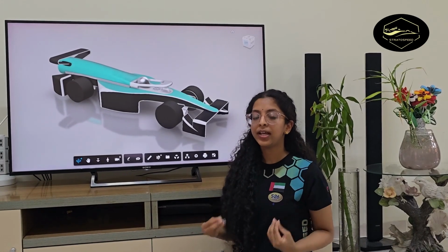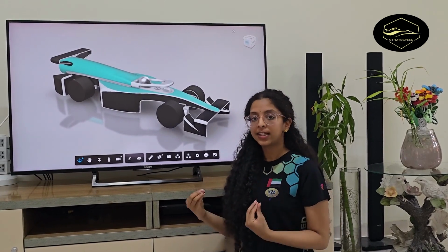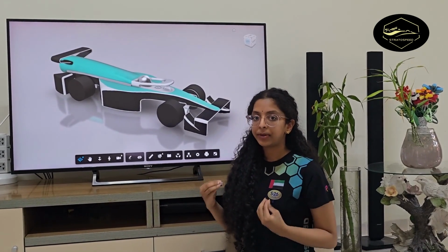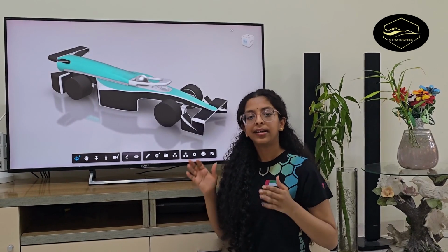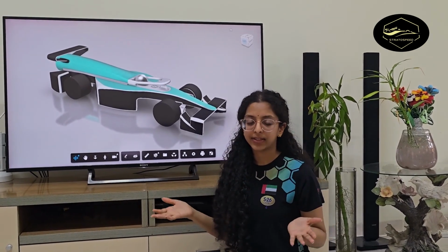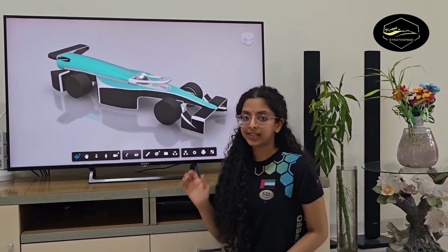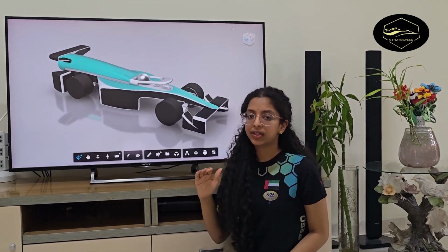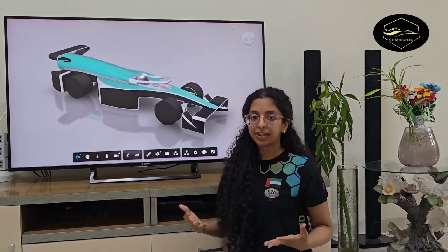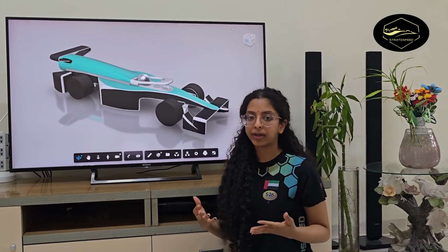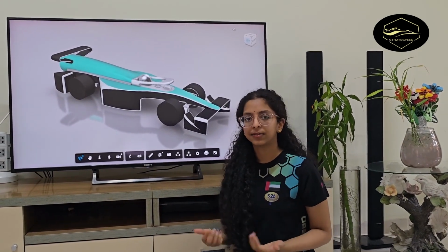So, for prototype B, we made two key changes. First, we narrowed the nose profile, the idea being to guide air smoothly around the chassis rather than letting it pile up and spill sideways. Second, we added fluid transitions between surfaces, smooth curves instead of sharp corners, especially around the air cartridge chamber and the wing mounts where airflow is most sensitive. With this design, the yaw moment issue was finally solved as the front wing added the necessary weight to the front of the body, balancing the center of mass.